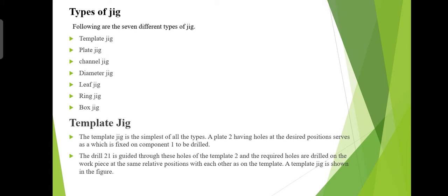The size of a jig depends on the dimensions of the part it is designed to hold. Small jigs are usually moved by hand on the drill press table until the guide or drill bushing is directly under the drill. The rotating drill is guided through the bushing and into the work by using a lever on the press. Large jigs are fastened to the work table and the drill is positioned to the bushing. A jig can have bushings of many sizes in it. Their use depends on the dimensions of the hole specified for the part to be drilled.